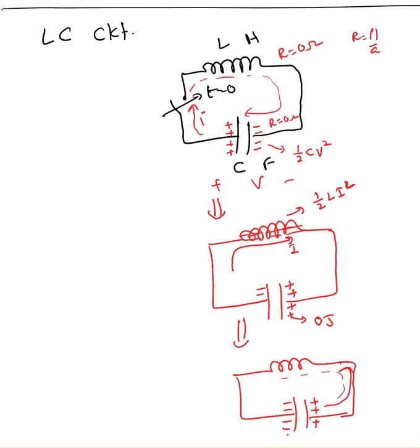Now can I say that the voltage drop across the capacitor is V equal to Q over C, and the voltage drop across the inductor we indicate with E. E is nothing but the induced EMF. That's the reason I'm indicating with E, but V and E are almost the same. E equal to minus L times di by dt.